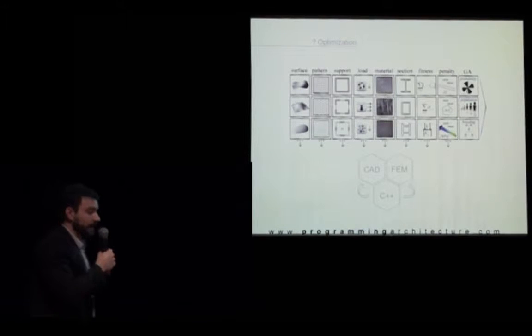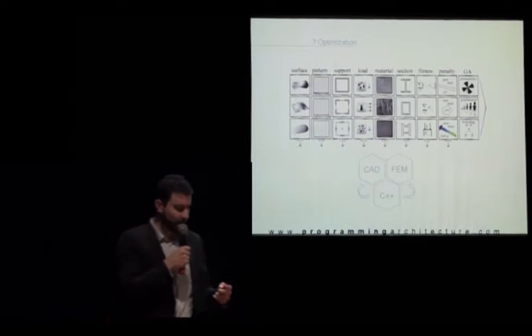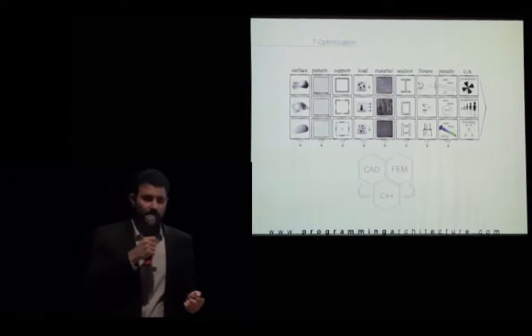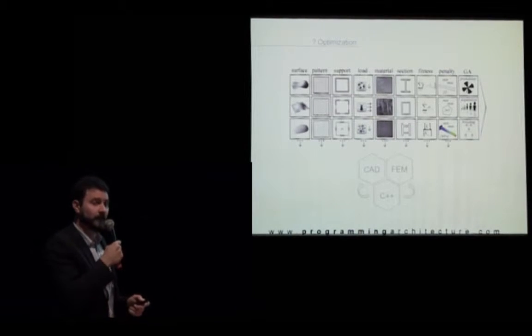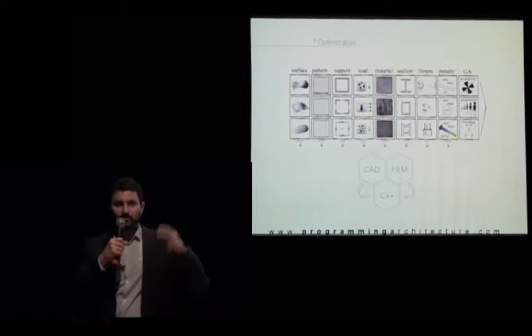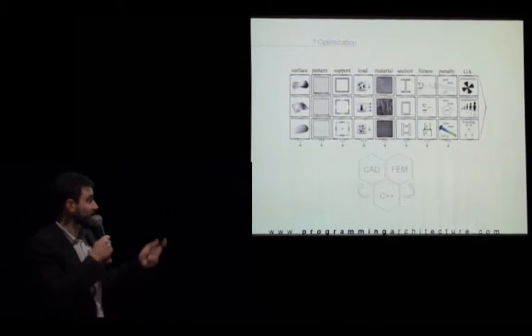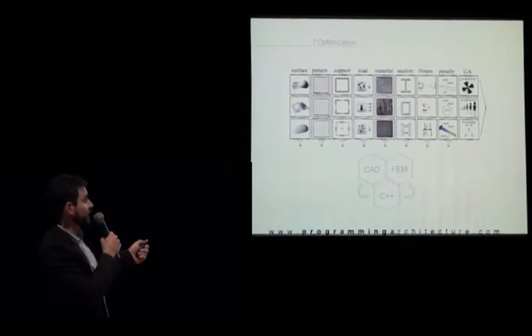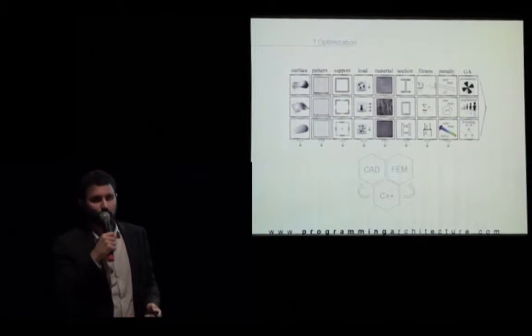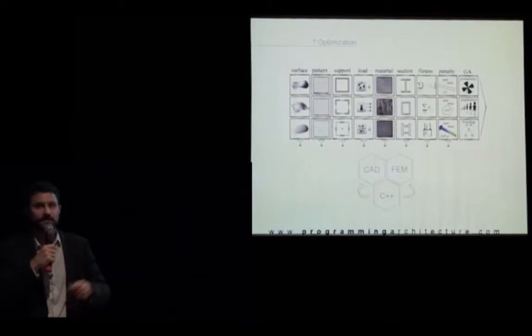The most important thing is that I made a very, very fast connection between CAD programs, in this case Rhino, and a static analysis program. It was all programmed in C++, and it was extremely fast. A structure of 1,000 structural members could be completely generated, prepared for static analysis, and calculated within 1/10 of a second. So within 1 hour we could actually analyze tens of thousands of structures.